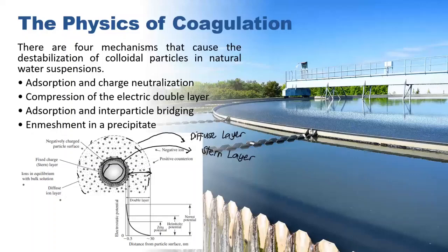So these are short-range attractive forces, which are the van der Waals forces. These van der Waals forces allow colloidal particles in water to stick together if they can approach close enough to one another. However, as the two charged particles approach, there will be a repulsive force between them, and the interaction of the ions in their double layers may prevent them from sticking together. So that is the physics of the coagulation.